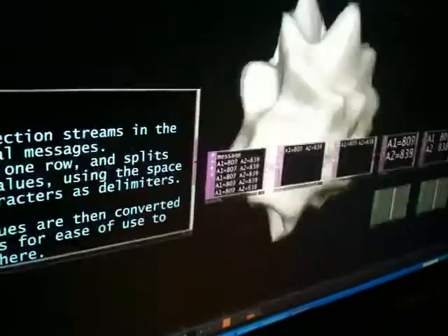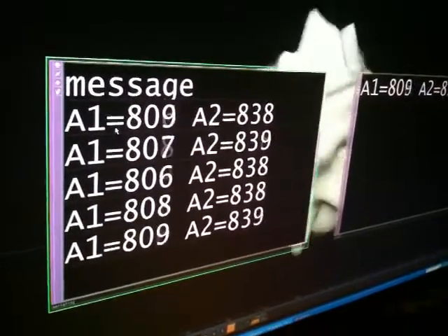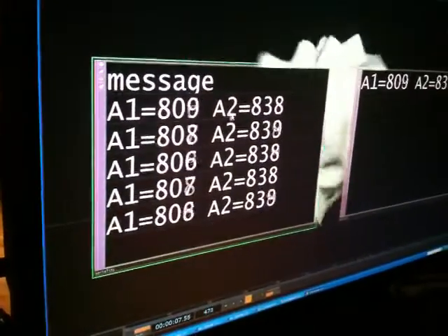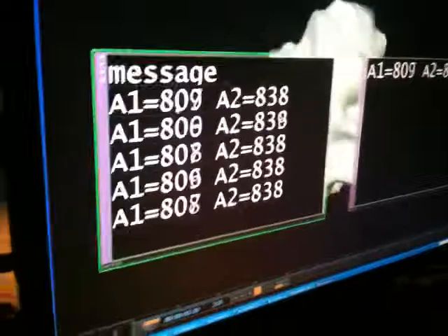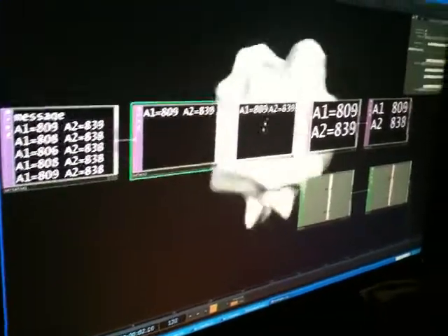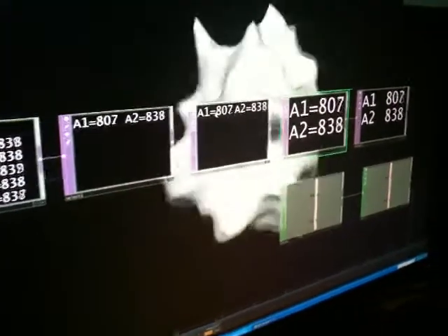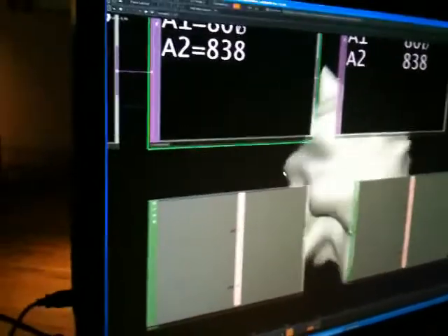And coming in from the Arduino, we use the same serial indat, and we see that it's sending these two messages that I've programmed it to do. So I've given it a specific format where each analog input outputs a label and then a number. Using a couple DATs, I just grabbed the first row to keep it simple, and I split it into cells using the space and the equals as delimiters. Then I convert it into a chop. So all that is just to have the Arduino name the channels and the values that are coming in.